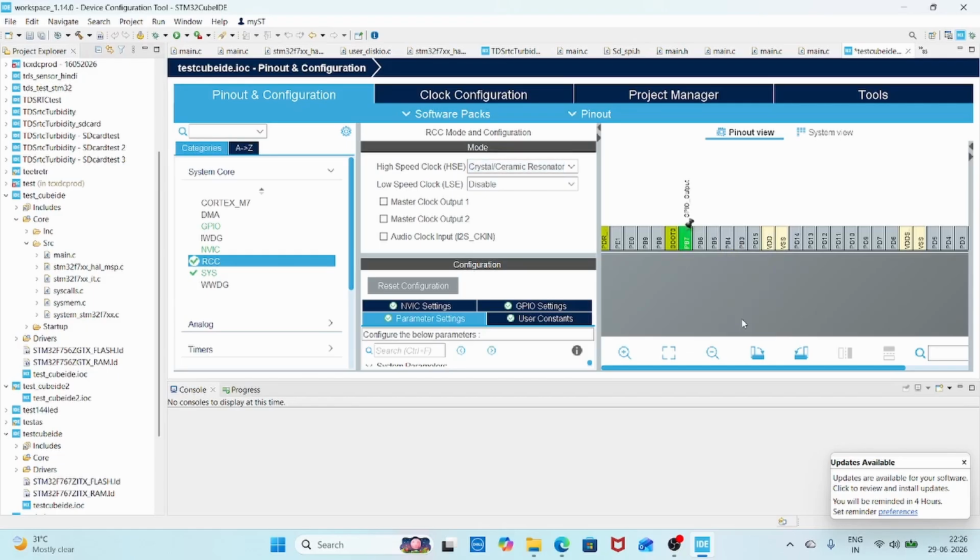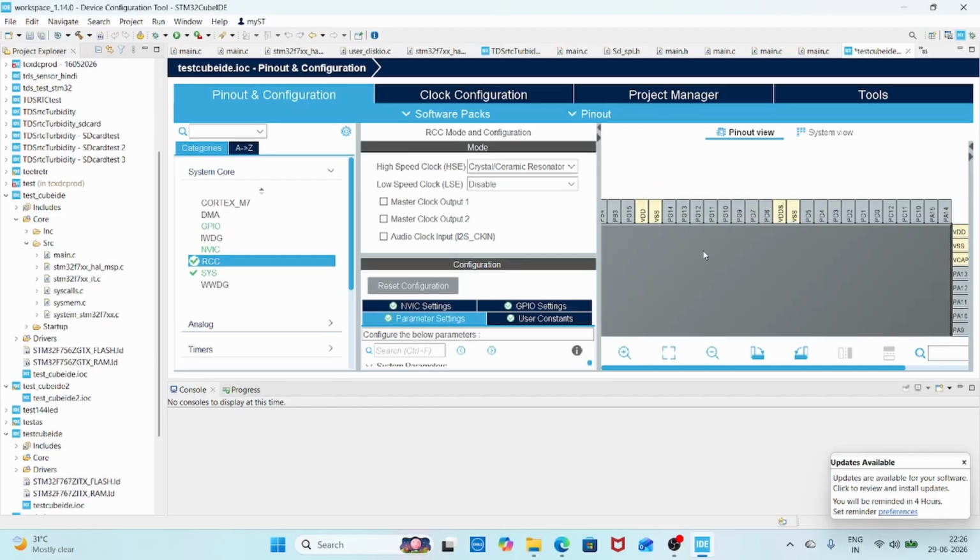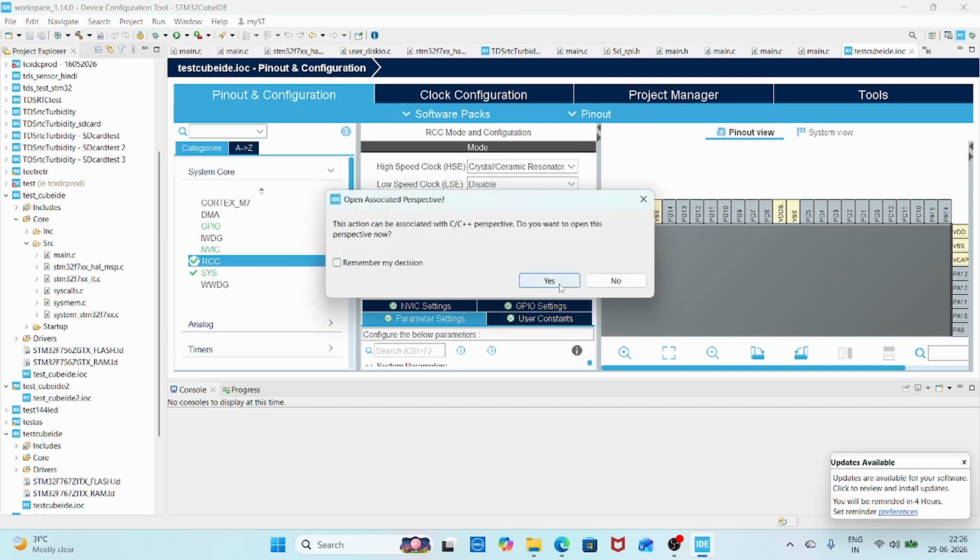And to turn on the LED, we have to write some voltage from the microcontroller. The direction must be output, right? The signal goes from the processor to the LED. So now output. This is a single pin configuration. I just configured a single pin. You can do this for multiple pins as per your requirement. And once ready, simply click over here. It will generate the code for you.